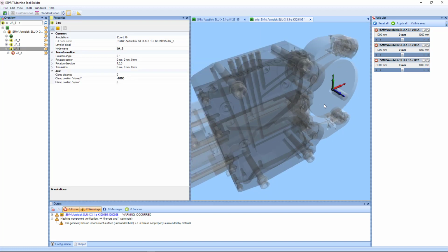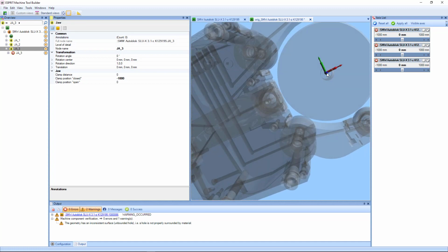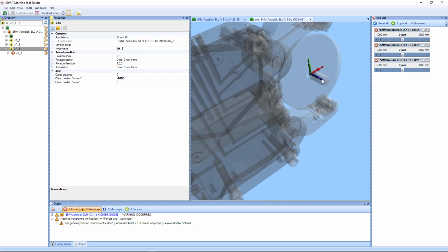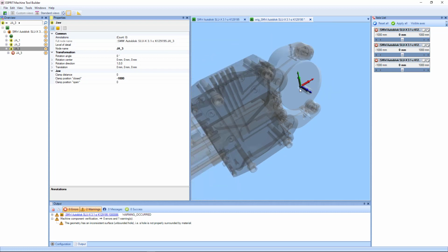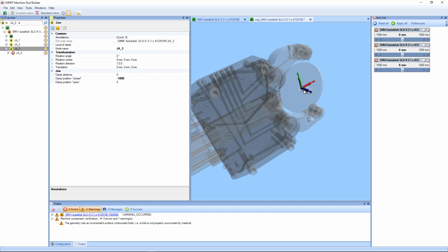Something that I actually neglected to mention when we were inside the TNG interface is obviously the Z-axis should be centered around the center of the clamping unit here. So you want to make sure that when you're in TNG, when you orient and position this, it's centered around the Z, at XY0, centered around the Z-axis. So then we're going to have these 3 linear axes here.